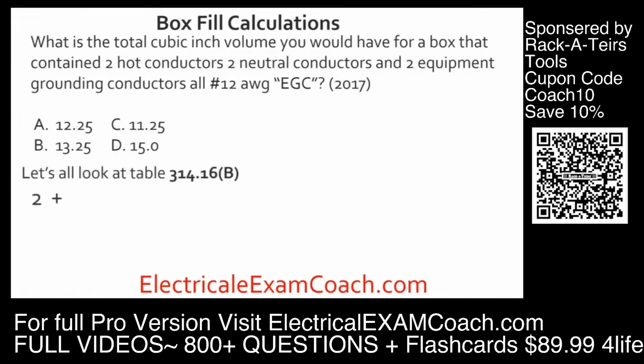Well, we know we're going to count our 2 hots, we know we're going to count our 2 neutrals, and all of the equipment grounds count as 1 total. We would have a total of 5 cubic inches. We do the math for 12-gauge conductors, and we end up with 11.25.